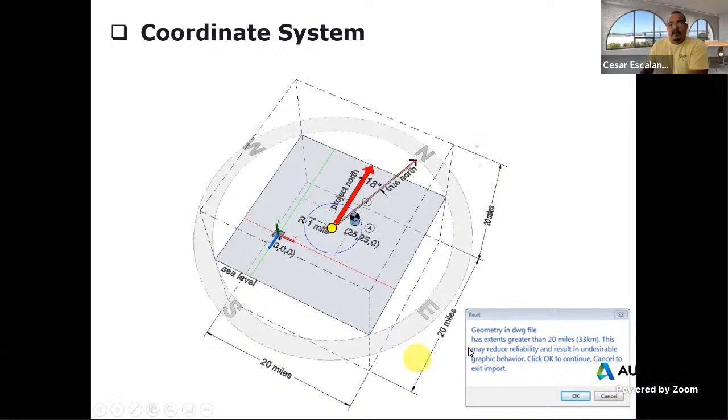and within the coordinate system, we have 3 points that are part of the coordinate system. And this is what makes Revit a little bit confusing, because in AutoCAD, things are pretty straightforward. There's only one origin, 0, 0. And that's it. You send that email and there's no question about where the origin is at. But in Revit, we have points that we need to understand and that impact how we coordinate a shared location.